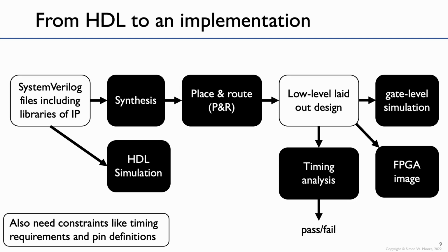And to give you one example, if you fail when you're doing ECAD labs to provide the pin constraints file, then the tool will just assume that it can assign pins any which way. The other thing that the tools can do is look at what's connected, and it can do optimizations during place and route and synthesis.